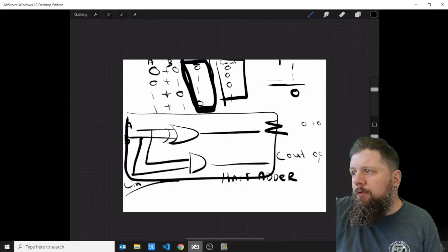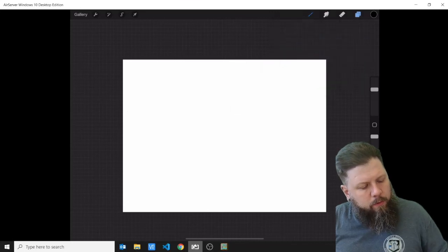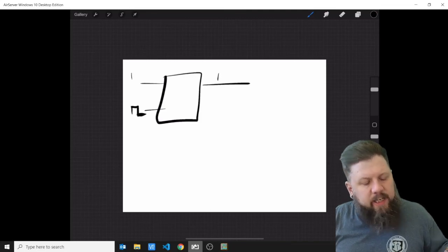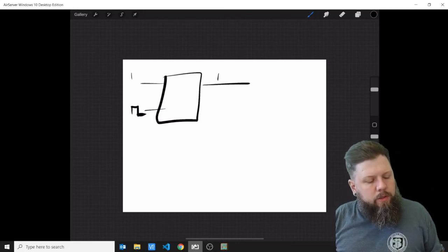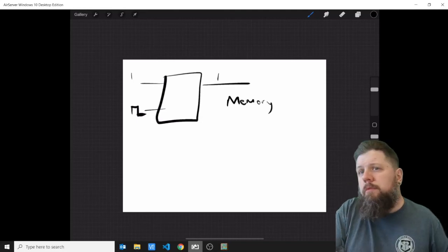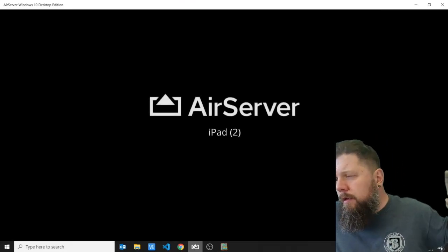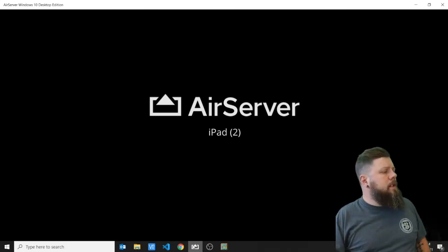And what I want y'all to think about too, look at adders and look at flip-flops, like memory location. Okay? Because what we want to do next is we want to be able to clock in a piece of data. So if we have a 1 right here and we clock it in, then it stays a 1 until we clock in another piece of data. Okay? So that's how we're going to start storing some of this information. Okay? But we're going to build it out of ands, ors, and nots. Cool? So those are 2 things I want you to read about for next time: half adders, full adders, and as much on flip-flops as you can. Okay? All right. Y'all can help each other get caught up.